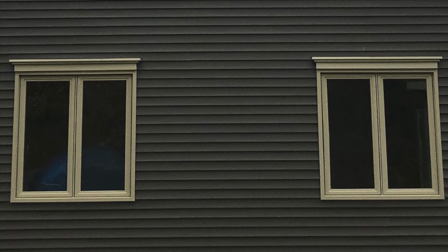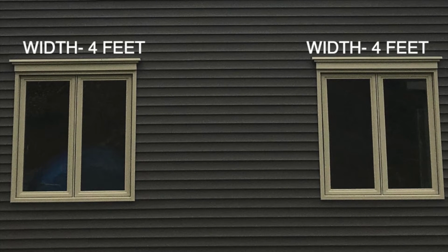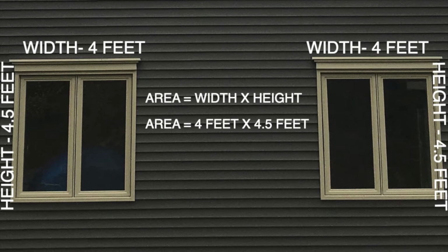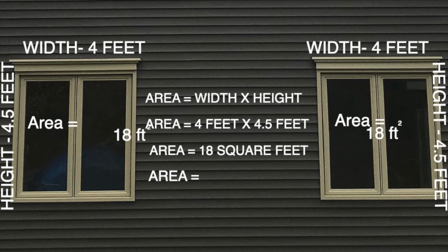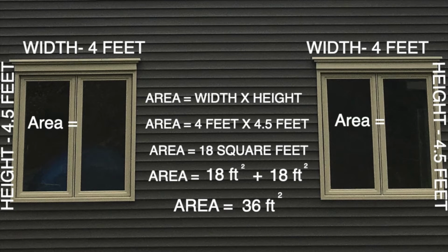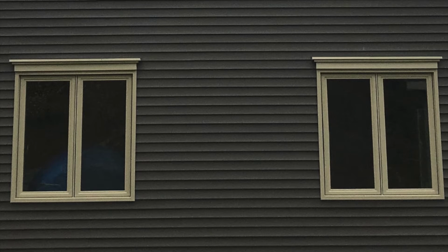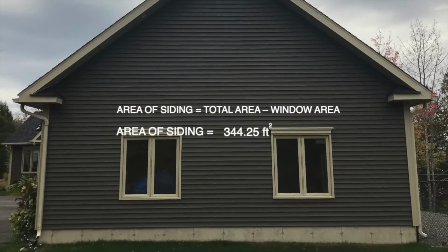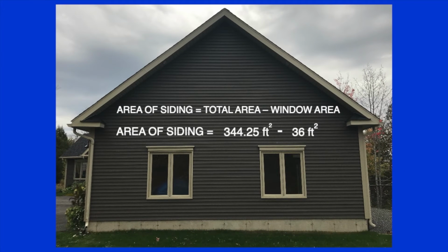Because each rectangular-shaped window is 4 feet wide and 4.5 feet in height, a simple area calculation reveals that they have an area of 18 square feet. Together, the 2 windows have a combined area of 36 square feet, which can be subtracted from the total area of vinyl siding needed to cover this section of the house's exterior. So, the actual surface area of siding required is 344.25 minus 36, or